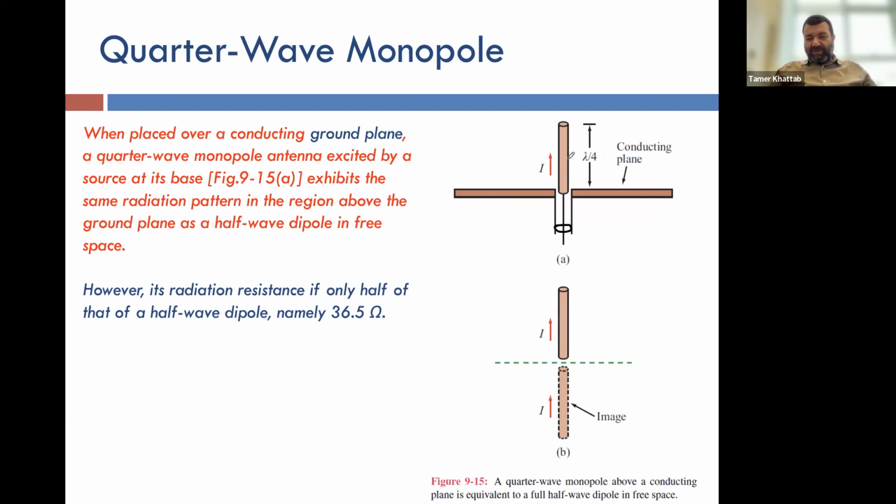The end result is that when you have some setup that has some conducting material close to a grounded conducting plane, the final analysis is equivalent to removing this plane completely and considering as if there is a reflection on the other side. This is a virtual reflection that does not really exist. We call that the image, and the method of analysis that uses this is called the method of image.